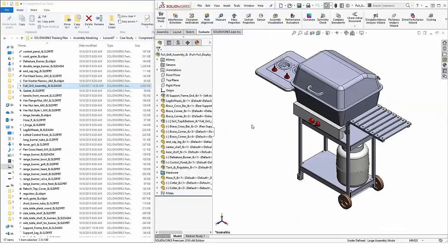And most of the time, that's not going to affect you as a user. Your drawings are fine. Your assembly still looks okay as long as you're not zooming super far in, and you're a lot better performance-wise. That seems like a significant impact. Huge impact, definitely. When I did this test, I was pretty surprised, actually, how big of an impact that was.